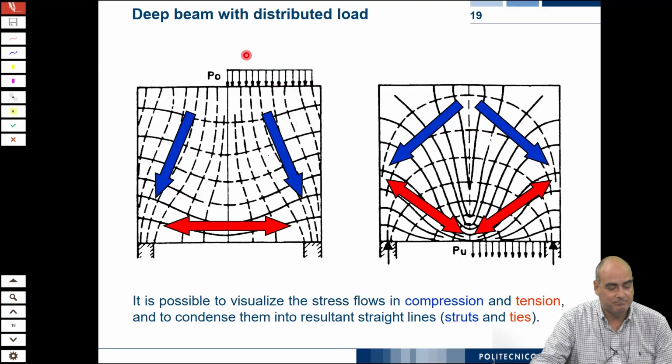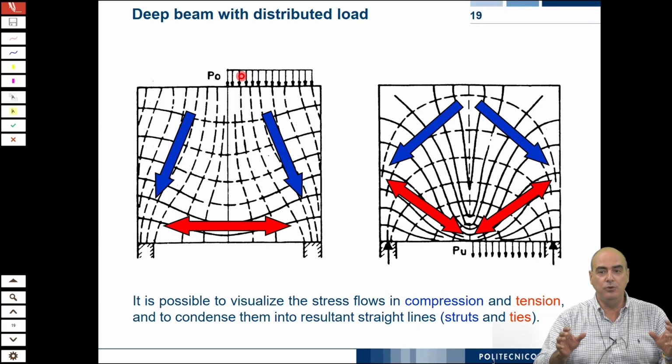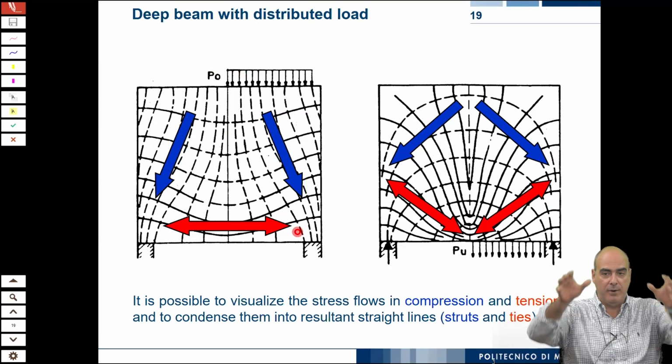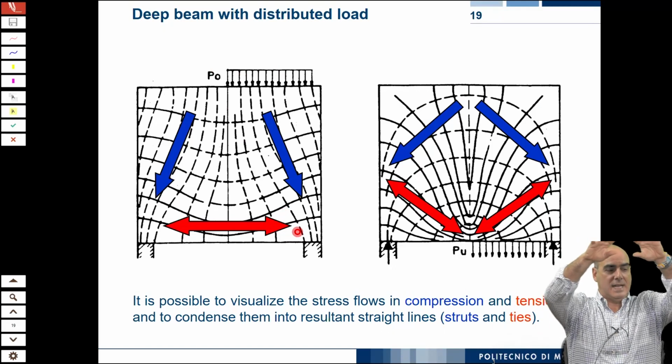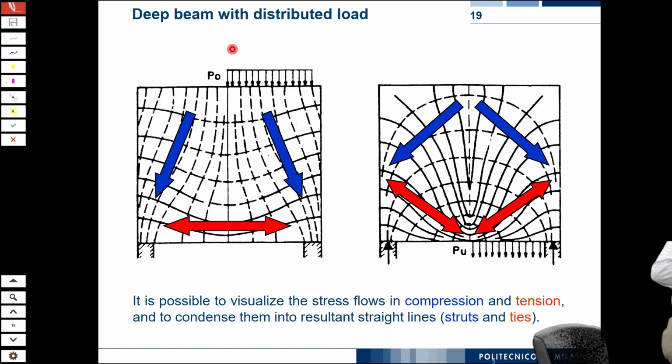But so, how do we imagine this? Okay, here the stress field is drawn, but we can imagine, for example, that we have this load applied throughout this width to this span here. How do you imagine it goes to the support? Well, you can imagine that it starts from the wall width you see here, starts narrowing, and conveys to the support.